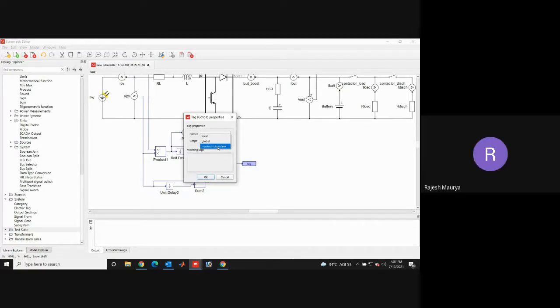If you remember, first we took the inverter, then the motor, and then the battery. We made that part as electric vehicle, and then we developed a charging system for that electric vehicle using a grid. We created a subsystem of it: one subsystem as electric vehicle, one subsystem as grid, and one subsystem for the charging part. So there were three subsystems in that model, and over that model we have masked it. We have taken an image for the electric vehicle or for the charging station, and we have placed that image onto that particular subsystem.